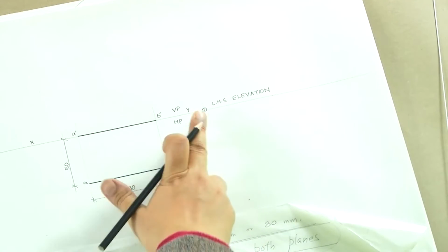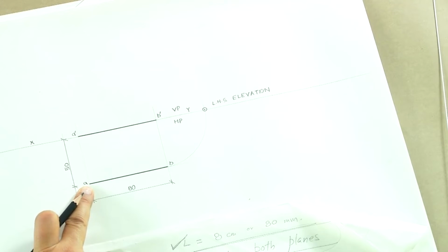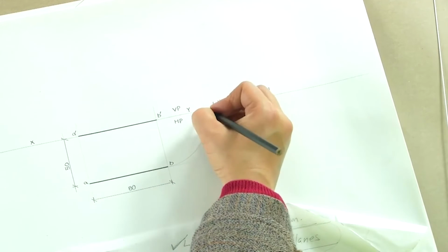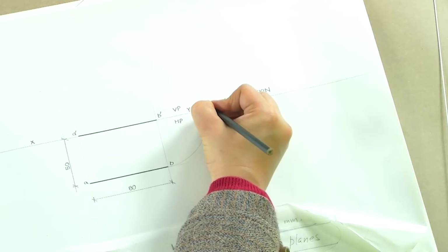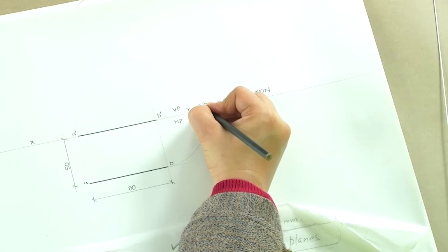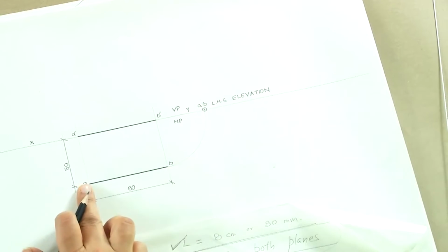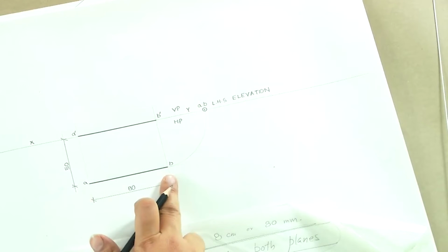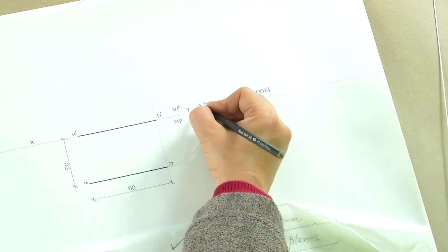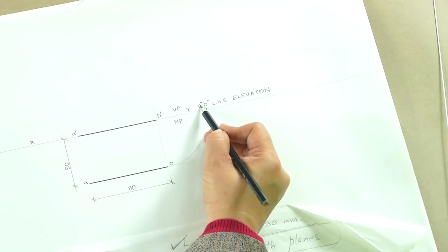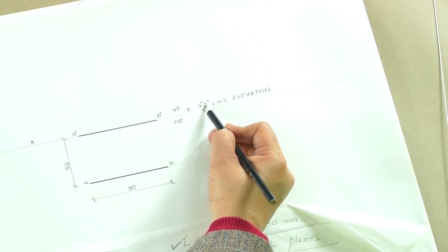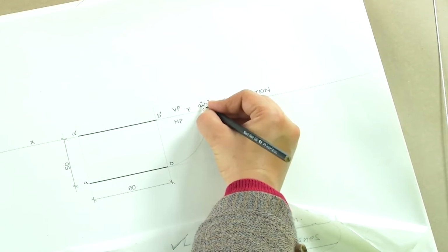And what is this point? This point is actually AB. So, we are actually seeing this A, B. Now, AB is the nomenclature that we use for the plan. So, we will either write A double dash, B double dash, which means that A is in the front and B is at the back. You could also put a bracket here, either of the two.